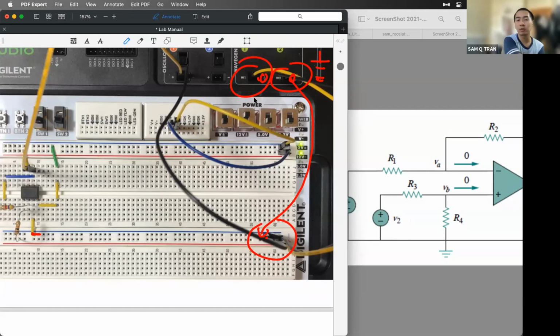All the ground nodes from the voltage source share the same node along with the ground node of the oscilloscope, then they are ground. The ground is just depending on your reference. For example, if you put the ground node somewhere with 1 volt, then your voltage will vary from 1 to 13 volts instead of 0 to 12. So the ground node is just wherever there's no voltage, so just 0.